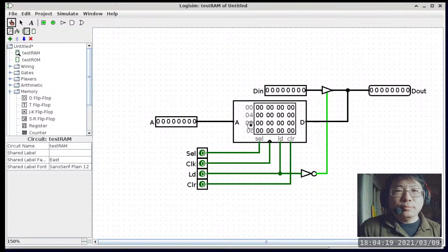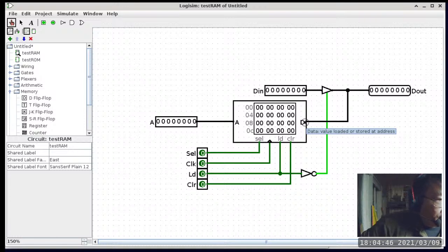All right, so RAM has an A port just like ROM, so it serves exactly the same purpose. It allows something outside of the RAM component to specify an address, so that we can say which location we are talking about. So it's kind of like the page number in a book. Okay, so the A port allows us to specify which page, and then the content of that page is presented or input through the D port in this case.